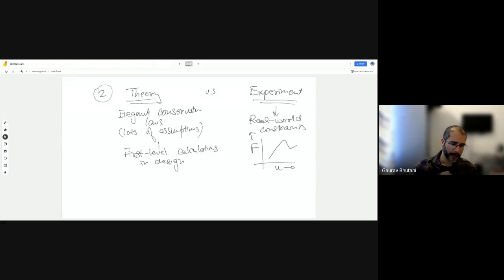So if I get a graph like this, when I want to design an aerofoil of a larger scale, I can use the scaling ideas, and then I may be able to calculate the force for a given speed. That will help me design an automatic pilot system, because it will tell me what kind of force will increase. So I have to increase the thrust accordingly to maintain a constant speed, for example. Okay. But the problem is there's no generality.